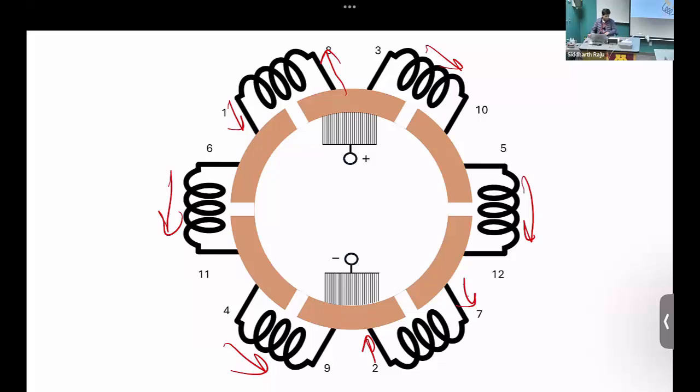But during this commutation process, 1/3 of the coil, in this case for a 6-slot winding, is being shorted. So when the commutation happens, when you're rotating at 100 radians per second, 10 volts would have dropped to 6.66 volts, right? 20 volts would have dropped to, whatever that comes out, like 14.44 volts, right? So it will be the same 1/3 voltage drop, 33% that drops. So that won't change, but the magnitude would be different because the EMF value itself is different. Okay? Any other questions? Yeah.